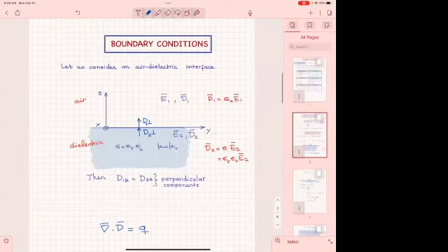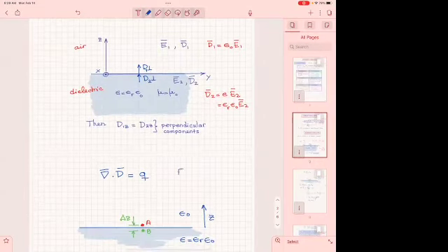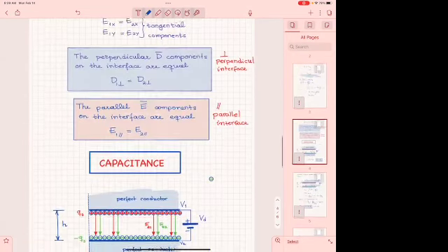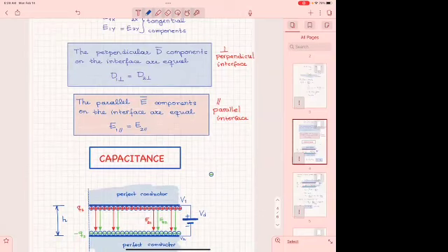So practically, you need to remember, so this is the explanation in 1D. To remember that when you have an air dielectric interface, the normal, planar, the perpendicular components of D are equal, but the parallel components of E are equal through the interface, are continuous through the interface. Okay, any questions? We are going to use this quite a bit in the following.